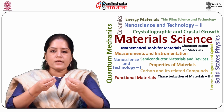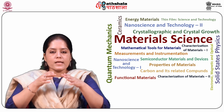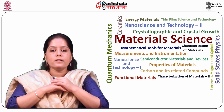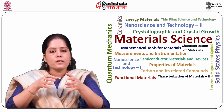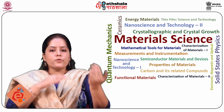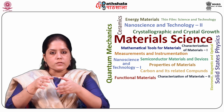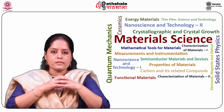Next, this oxide layer acts as an insulating material and can also be used as a protective layer. It is used for surface micromachining, acting as the sacrificial layer. We also discussed the requirements for the quality of the oxide layer, so that we can choose either dry or wet thermal oxidation. Lastly, the configuration and applications of the silicon oxide layer were further discussed in this module.